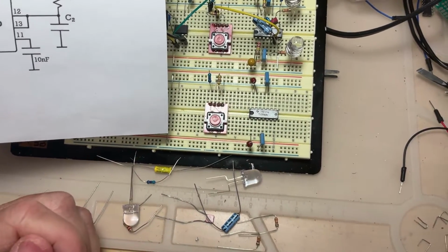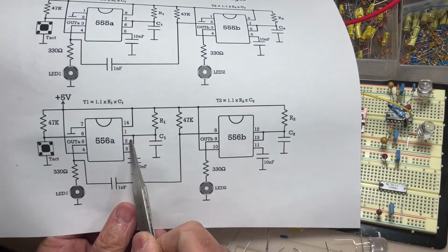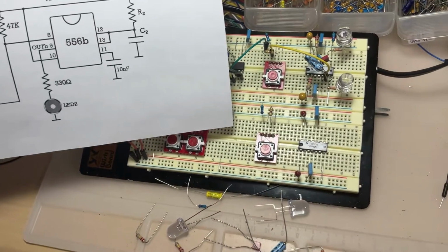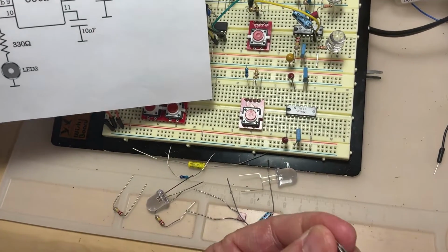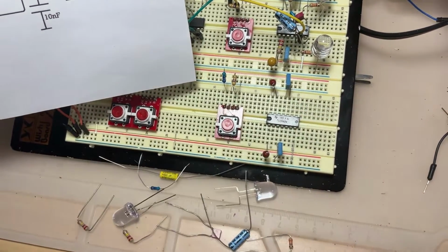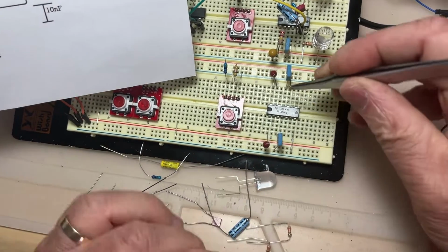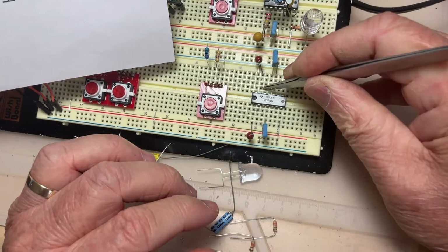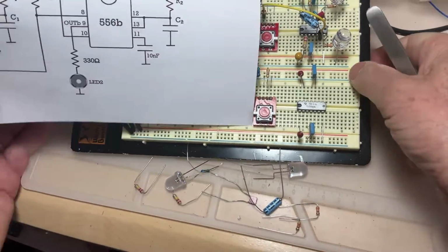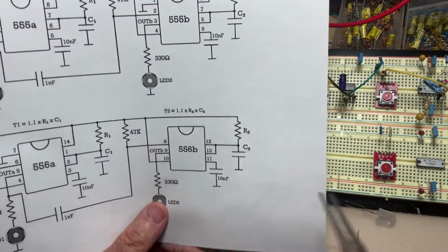So just to make sure, you are going to notice that the pins 1 and 2 are related together. The pins 12, 13 are related together. So let me just place a little jumper over here. 1, 2 are related together. And I'm going to place another little jumper on 12, 13 because they are going together. So this way, the two terminals 1, 2 and 12, 13 are going together.